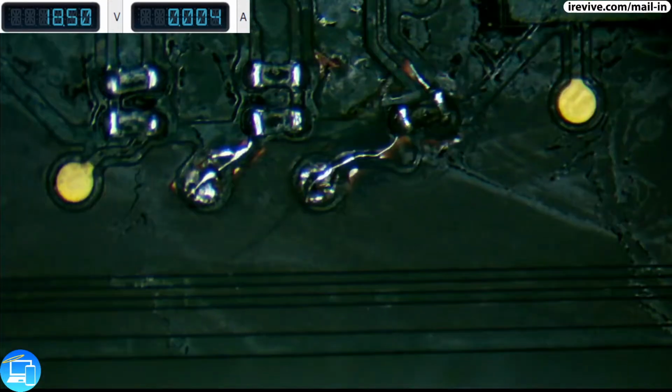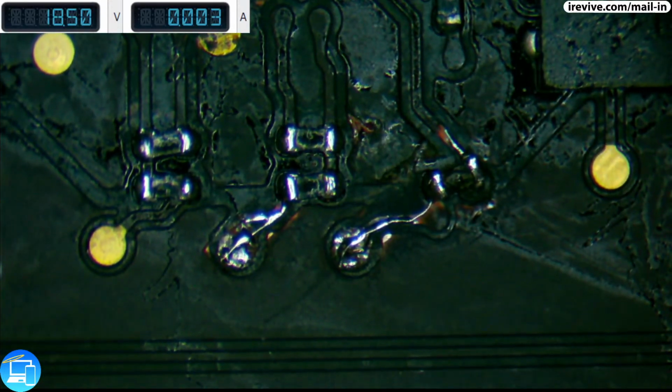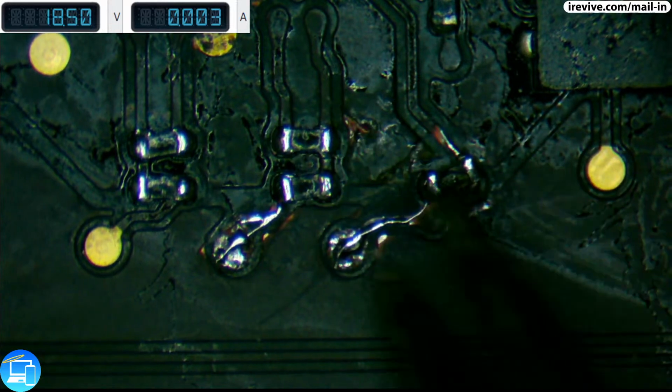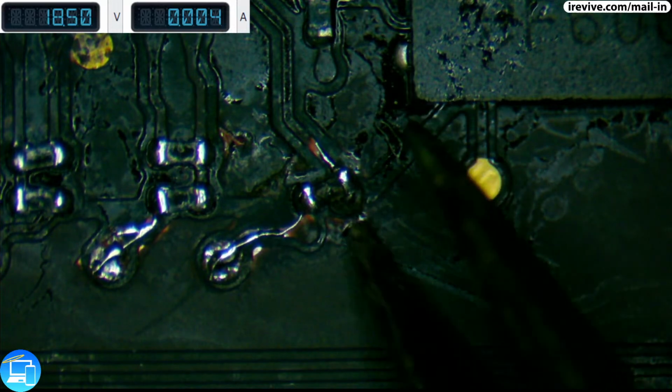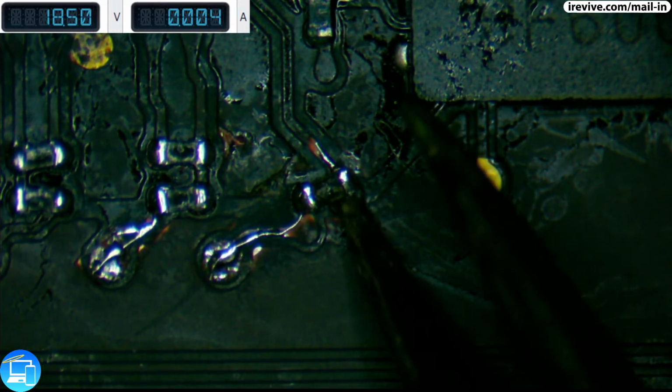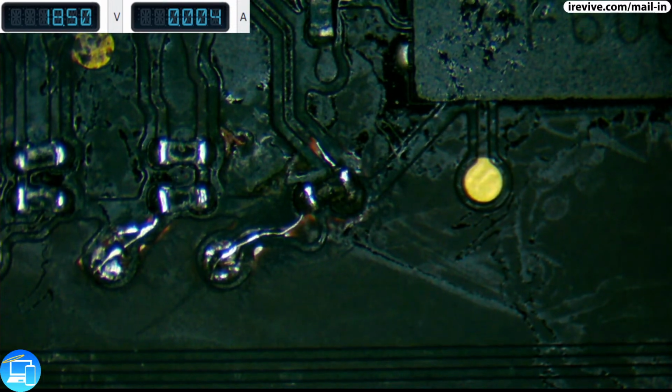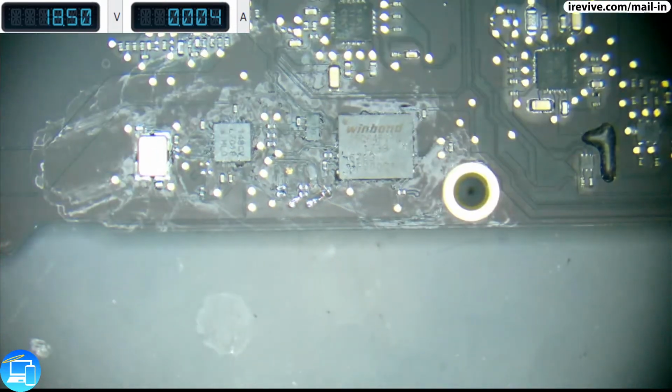And this is what we have. So that jumper wire down here is making a good connection. Here it's soldered right there, and then I can see this jumper wire is touching that trace, touching that part of the resistor, and I have a giant glob of solder that is holding the resistor to the jumper wire to the via. So, let's figure out if we fixed our MacBook.